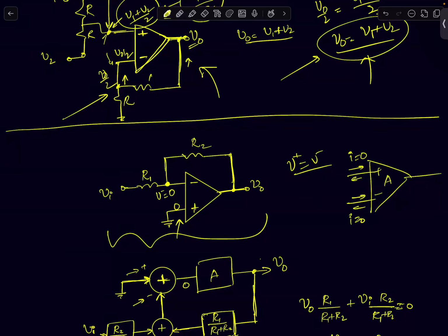Initially, amplifiers were built using BJT circuits. So those BJT circuits used to draw some input current. Generally those input currents, we call them offset currents and all that. But for the time being, I'm going to ignore that. I'll assume that right now in CMOS amplifiers, we don't worry about them. But in BJT amplifiers, initially, that used to be a concern. So that had to be taken care of. So right now, I'll assume that the input currents are 0. The amplifier is not drawing any input current.